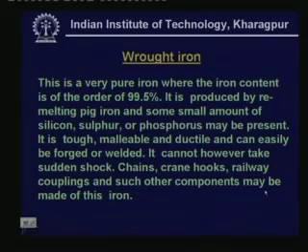What you can see is that these are very tough, malleable and ductile, and can easily be forged or welded. But it has a drawback: it cannot take up sudden shock. So if you are using it for static or quasi-static situations, then it is really a very good material.